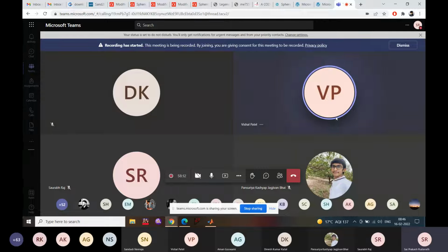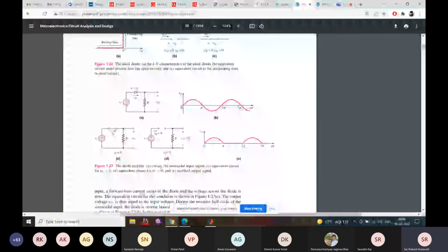Again, can you see my screen? We are continuously increasing the voltage from 0 to the maximum value, then it decreases again. At 0.6 at both ends, the diode should stop conducting, right? Yes, sir. So we get two cutoff points. One cutoff is at 3.4, and the other will be 180 minus 3.4. Yes, sir, got it.